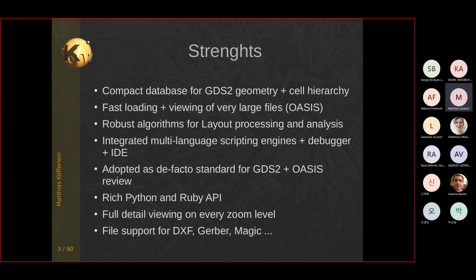What I had was very huge files, because we are close to mask, and close to mask, file sizes explode, because you start doing things like dummy tiling, so you create a lot of dummy features on the mask, which are supposed to support manufacturing, like density leveling. So you get very, very huge files. We are talking about 10 gigabytes, and today even advanced nodes speak of terabytes of data for a single mask.